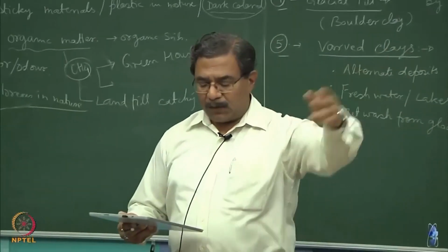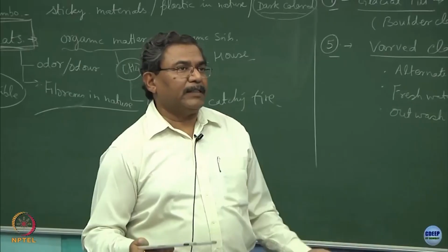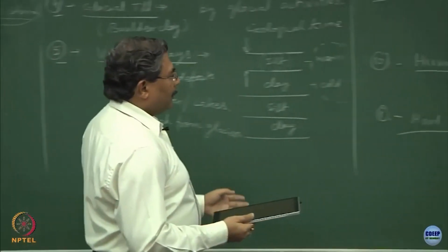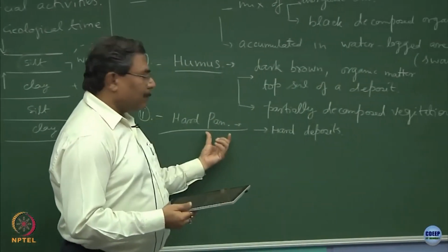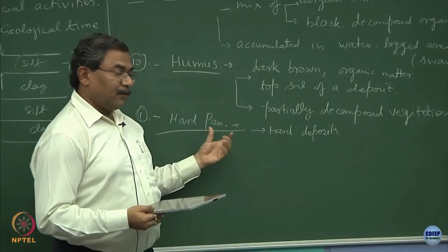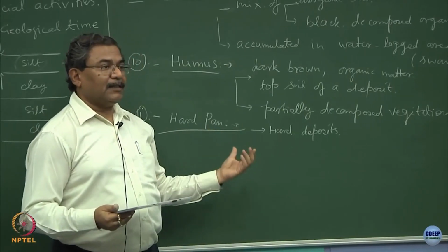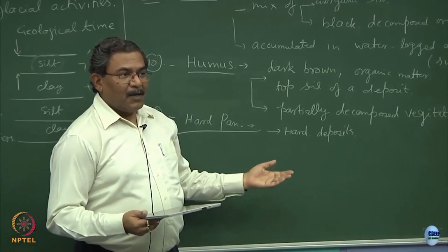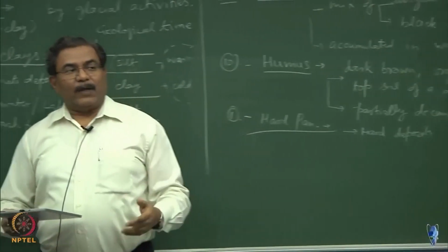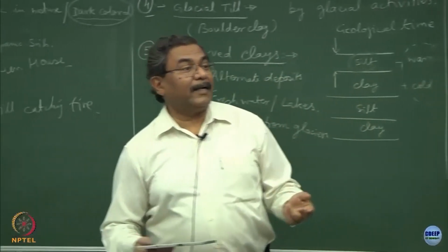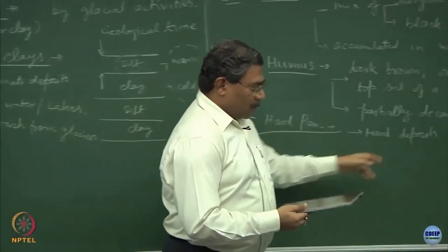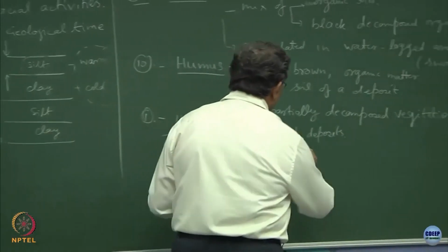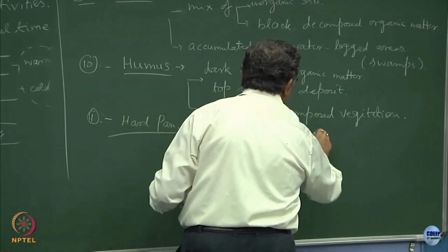So, you were asking this question in the very first lecture, where to lay the foundations. It may so happen that when I am doing investigations, I may come across this material or deposit, it is very hard and I might mistake this as a hard strata, rocks, clear. But subsequently when you excavate the soil, it might get disintegrated very fast, okay. So, this is the property, though it is a hard deposit having cohesion.